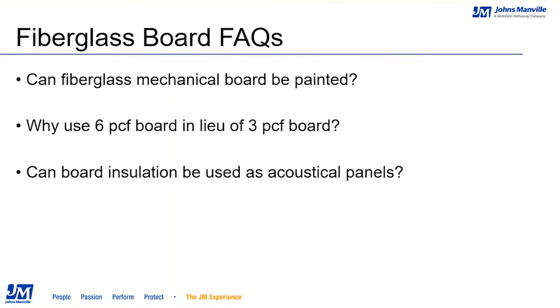Before Paul takes us through our next product offering, let's take a look at some frequently asked questions for fiberglass board. First, can fiberglass board be painted? Again, the answer here is the same as we discussed in the pipe insulation section. We would not recommend painting our insulation as it would void the 25/50 flame smoke rating and our manufacturer's warranty.